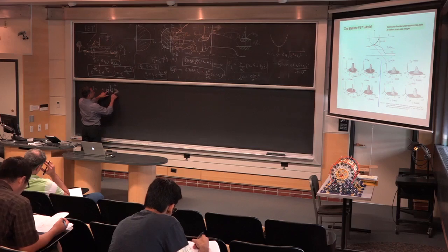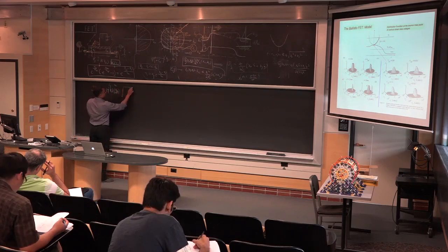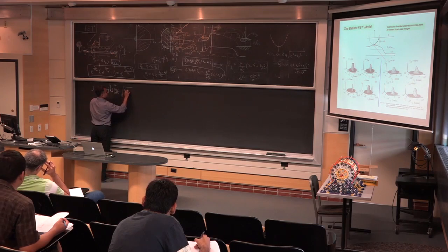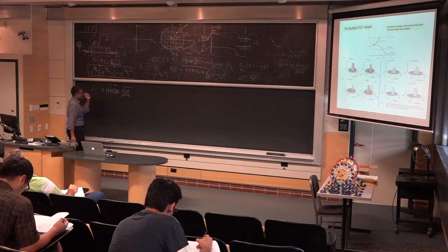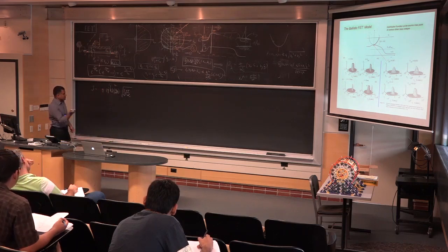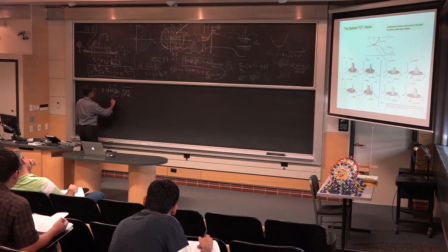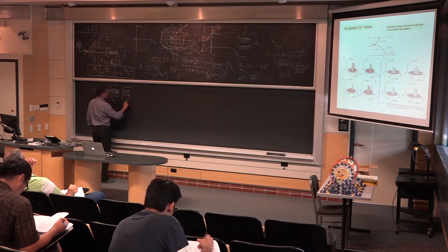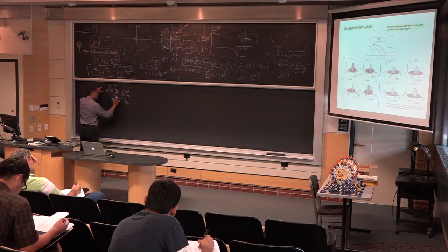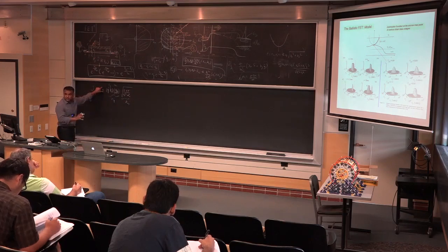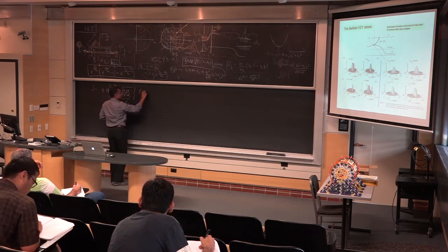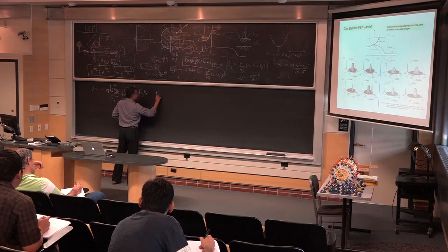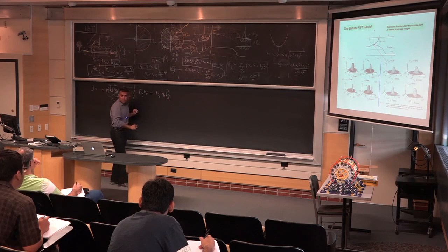Okay, these are things you can actually just write down from evaluating that integral. All these factors just come out of the integral. So these are natural quantities. This is what we call n quantum. This is what we're calling some sort of an injection velocity. Charge times density times velocity is current. And the factor that depends on all the voltages is sitting here: f half of eta source minus f half of eta drain. So this is all the controls.